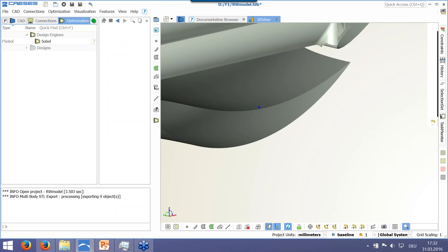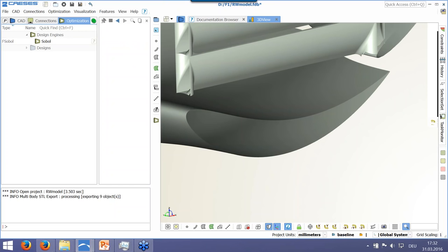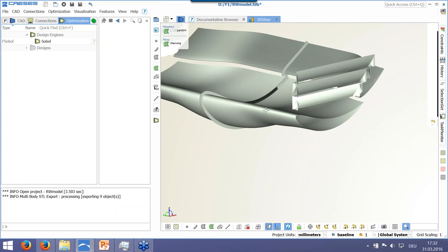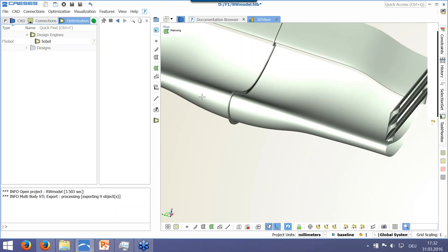It's a profile that is characterized by a set of parameters. Like I have said many times before, it's parameters that describe our geometry. Here it's the NACA 4-digit, with the camber position, the chord length, and the thickness. So you have to describe how these parameters are distributed along this way, along the span of the wing, or along this path.